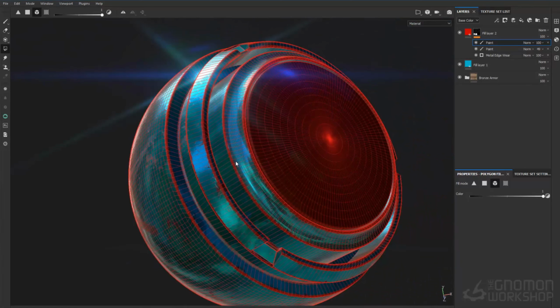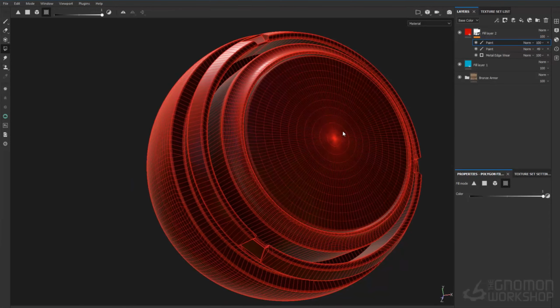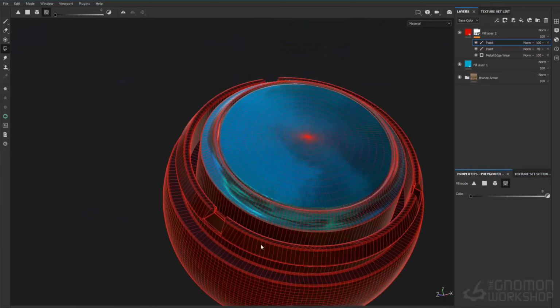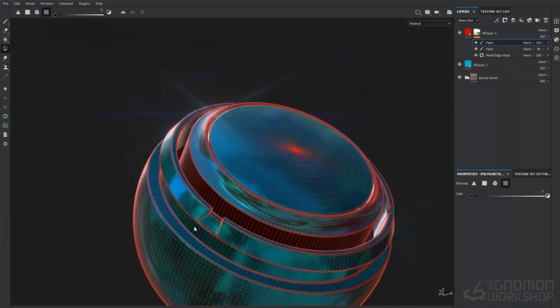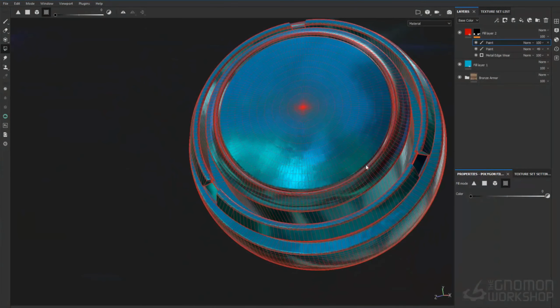Meaning per object, it's not going to be like what you have in your scene, it's going to be any polygons that are physically attached to each other. But I can also select per UV. For example here, I'm going to be going back to white, and I can perfectly select what I want per UV pieces. I'm going to show you a little trick later when we change the bake, okay?